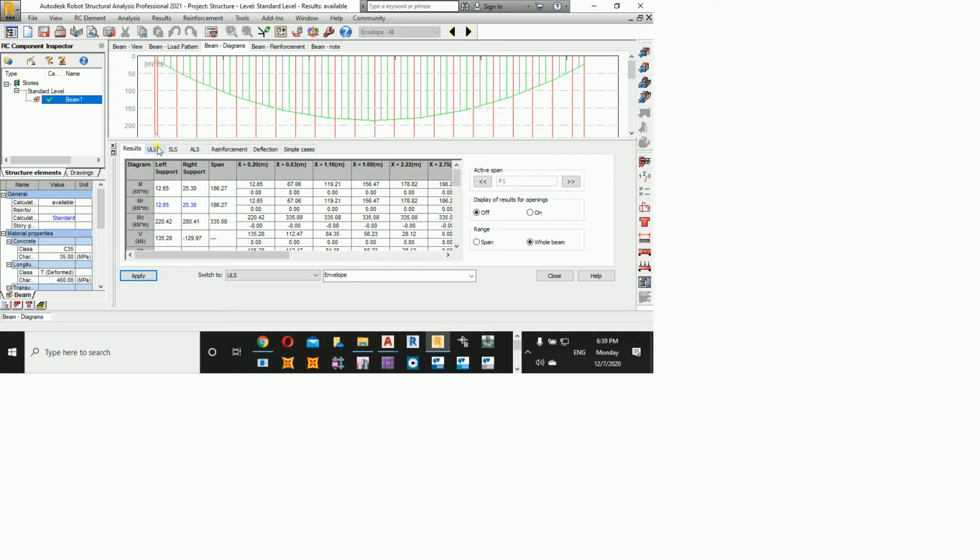Now when it comes to deflection, if my weight is 100, will the deflection be calculated for 140 or 100? When I design the chair, the maximum limit will never change. It's 140, whether my weight is 80 or 100 or 120 or 140. That's the maximum ultimate load that can be taken. That's my maximum limit. Now, when it comes to deflection, if my weight is 80, then the deflection will be according to 80. If my weight is 100, the deflection is going to be according to 100.